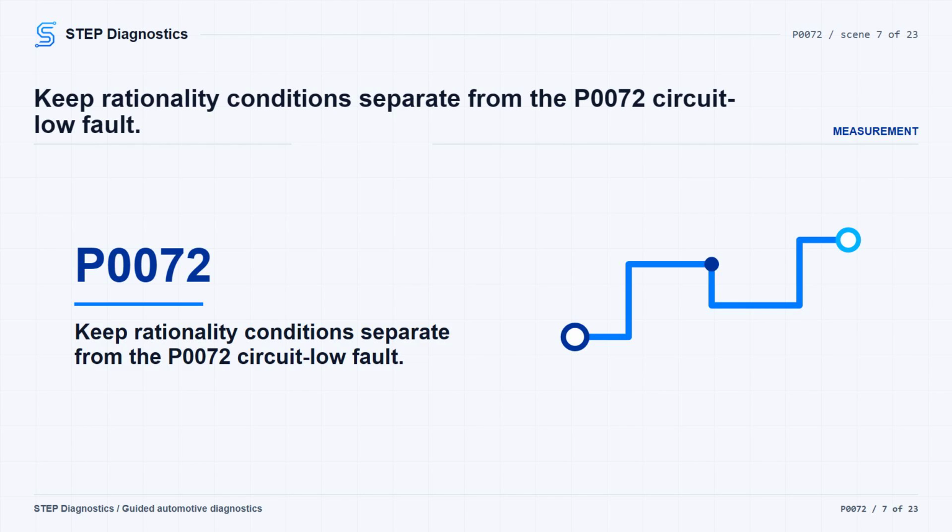It runs with the ignition on after an 8-hour cold soak on the previous engine off cycle, with ambient air, intake air, and engine coolant temperature values above -64 degrees C, -83 degrees F. A performance fault is typically not within 10 degrees C, 15 degrees C, 18 degrees F, 27 degrees F of the other engine temp sensors, so keep that separate from the low circuit diagnosis.